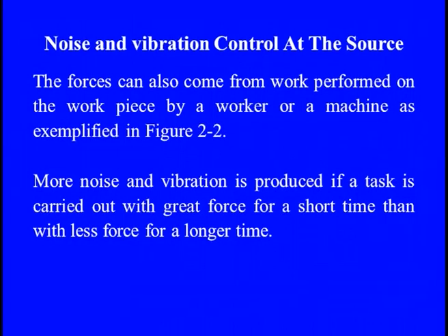So it can have any kind of nature. It may be the transient one, it may be the steady state one, or sometimes it may be continuous through reciprocating motions. The forces can also come from the work performed on the workpiece by the worker, or from any machine when it is rotating. More noise and vibration is produced if the task is carried out with great force for a shorter time than with less force for a longer time, because a huge amount of energy is involved when there are huge forces, inertia forces or any other kind of forces, even for a shorter time.